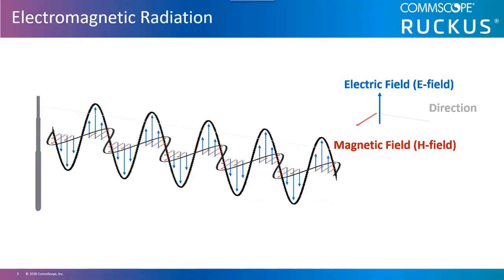Electromagnetic radiation. Electric and magnetic fields are perpendicular to one another, moving into space away from the source. Electrons moving in a current produce an electromagnetic field. The field produced by an electrical component is known as the E field. The magnetic component produces a field known as the H field. During a transmission, both of these fields propagate away from and perpendicular to the antenna.